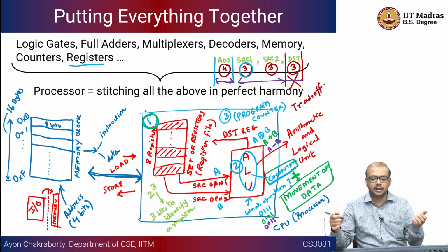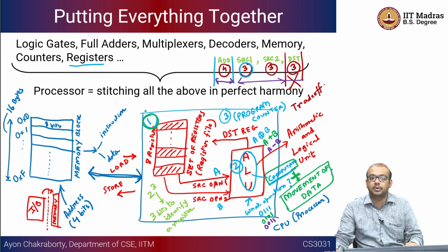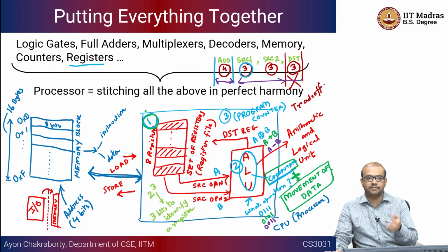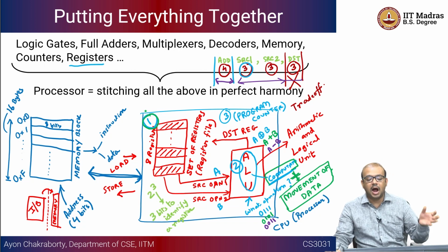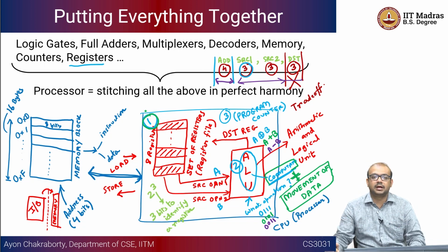All of you know that you will require a temporary register, right. So, you have to save the value of X in a temporary register, copy that to Y, and copy temp back to X again, right. So, this requires 3 register operations, right. So, how do you architect the system to make these register transfer operations possible, and what is a better or smarter way to do that inside the CPU? We will start with that.